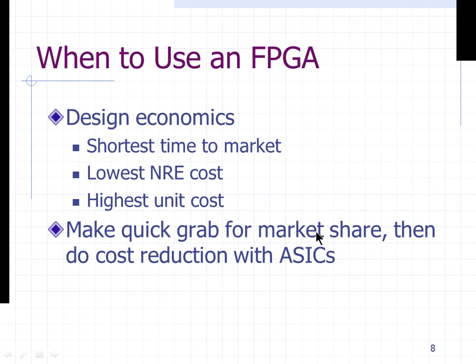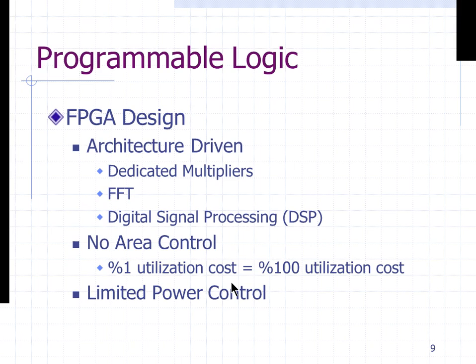Earlier, what teams or companies used to do was develop products using FPGAs and launch them in the market. Once customers get used to it, then you can develop an equivalent ASIC for it and try to reduce the cost of the product or improve your profit margins by developing an ASIC. Nowadays, FPGAs are also used in full-fledged products, and people keep using them. You don't have to convert it to ASIC every time. Sometimes they still do it, but not every time. So this was cost related.